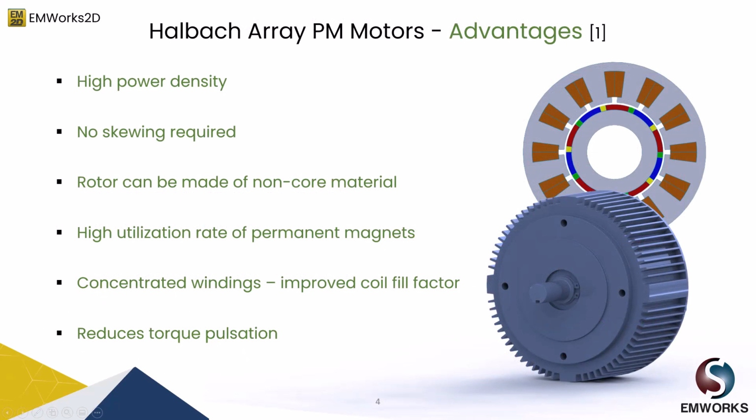Moving ahead with Halbach array arrangement, compared with the traditional motors, Halbach motors have many advantages. First is high power density. If we compare with the traditional permanent magnet motor structure, the magnetic field intensity on the air gap side is greatly enhanced because of the superposition of the parallel magnetic field and the radial magnetic field after the decomposition of the Halbach magnetic ring, which can effectively reduce the size of the motor and enhance the power density of the motor.